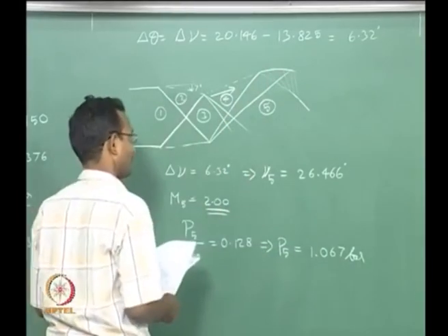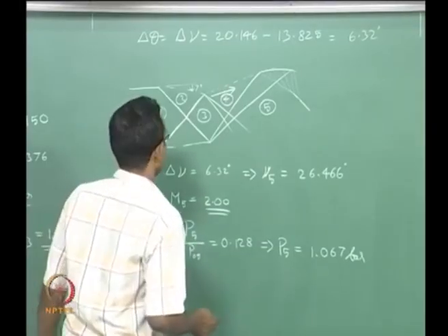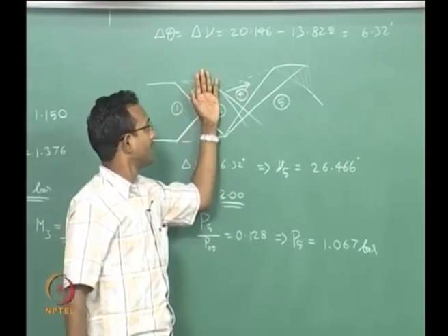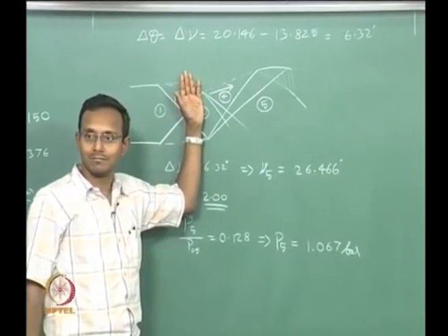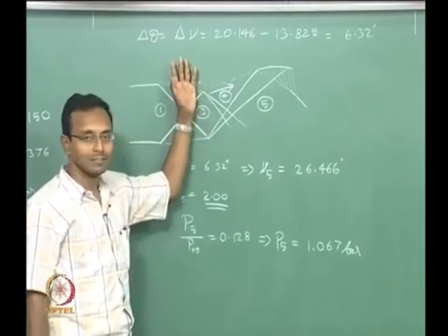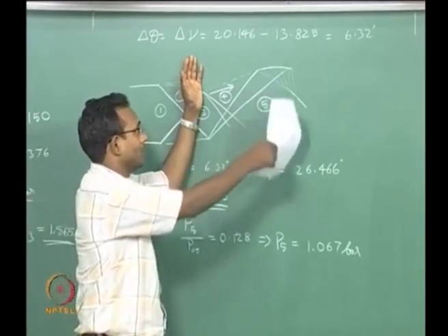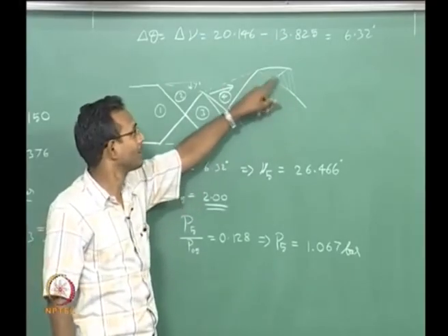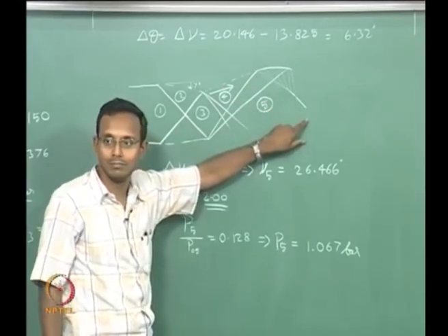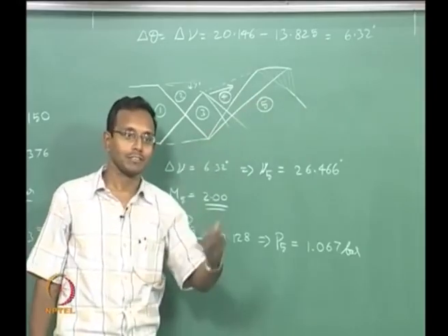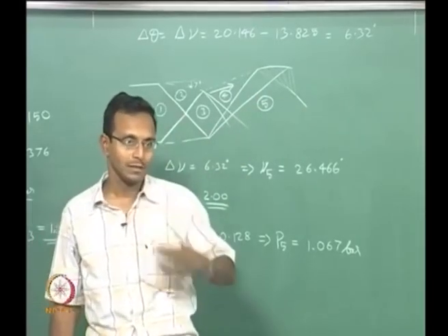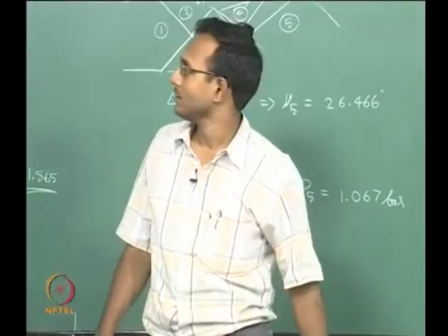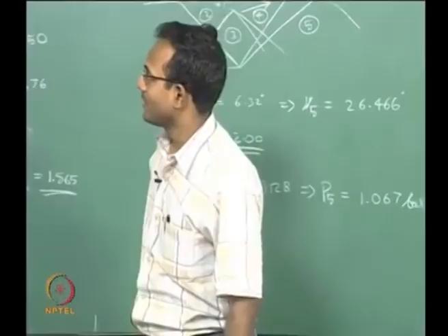Okay. So the same process I can follow if I want an under expanded jet, which will start like this. Exit pressure will be like condition 3. From here I will just say I cannot go past this point currently. I do not know how to solve for compression waves coming together and forming a shock. We will leave it there for now. Yes. But we started with an 80 bar P0. How will you get 0.1024? It's not 0.1. Okay, we started with an 80 bar P0.